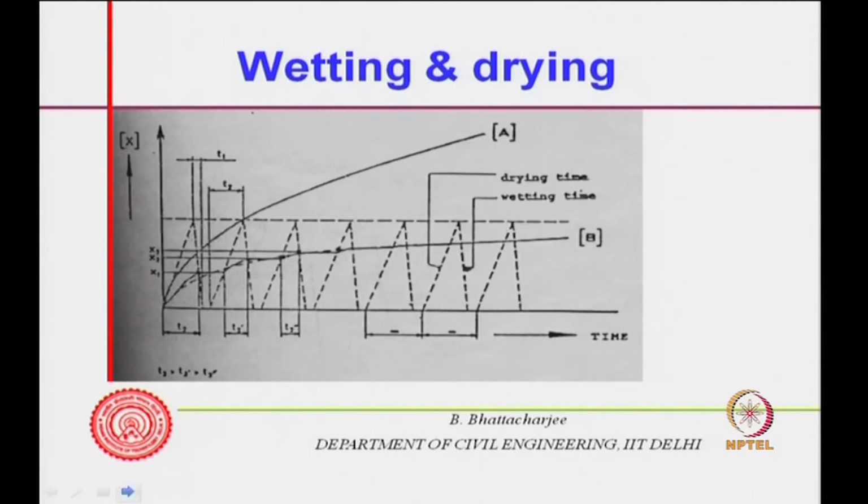So, then the carbonation front will progress in this manner. In the first cycle, one can approximate the drying and wetting, because wetting is more or less instantaneous, then again drying and wetting, then there is a small gap, drying and wetting, small gap, drying and wetting. So, this is the conducive moisture condition during which carbonation will progress. Carbonation progresses here, but then it will not progress further till this point, again progresses in this manner, stops here, progresses in this manner, and it follows till it reaches the cover depth,